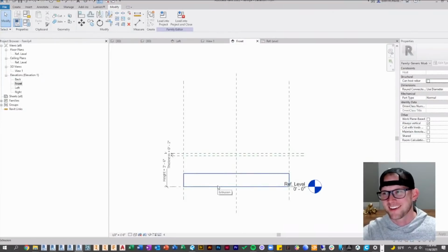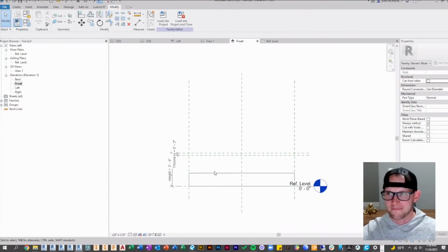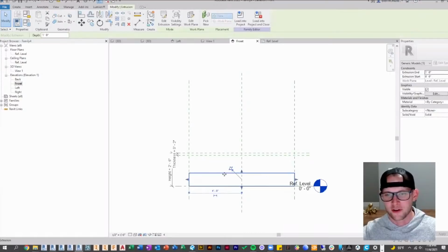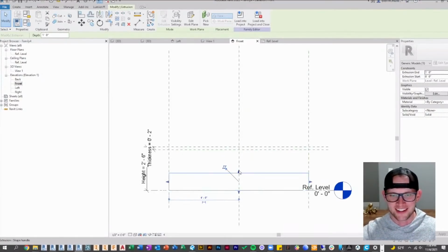That is definitely a good tip: don't press those locks unless you know what the hell they're locking to. I think when I was first learning, you just learn to lock them and you think you know what you're doing. You're completely oblivious to all the things that could be causing you problems, and so you're shocked at the end when nothing's working. Like, what the hell is Revit doing? I didn't tell it to do this.